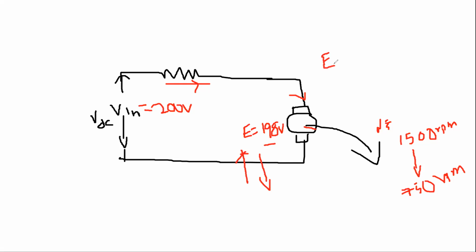Mathematically, how will you derive it? Your faculty will draw this equivalent circuit, and by KVL application and induced EMF E, you will get the final equation: E = PØZN/60A. Yes, PØZN/60.